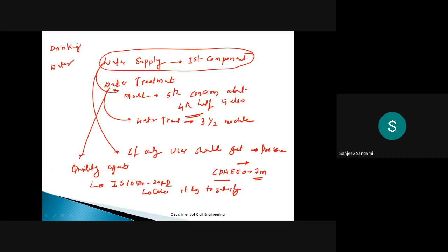All of the drinking water quality standards have to be satisfied. For example, you might have studied one simple component, that is pH. pH is one component in this code. As per these norms, 6.5 to 8.5 is what I have to maintain. This is the standard for the pH parameter according to this code.